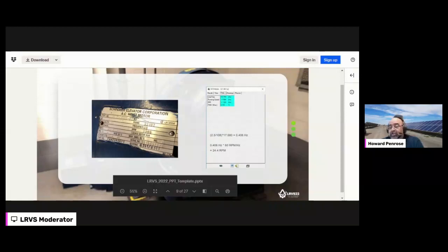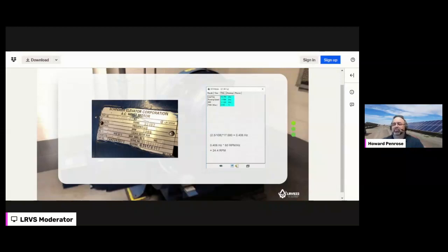Now, one of the challenges with electrical and current signature analysis, I'll use those interchangeably, so for this one we're primarily looking at current. As you can see on the nameplate, it says bearings 6311 and 6311. Well, they're both turning at the same speed, and I'm seeing both at the same time.